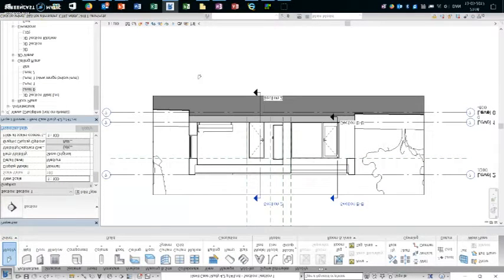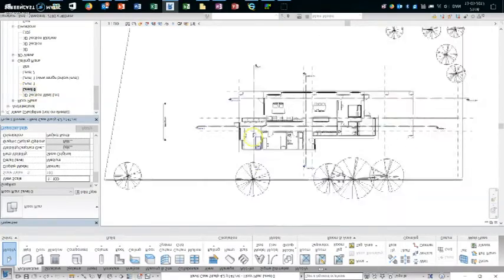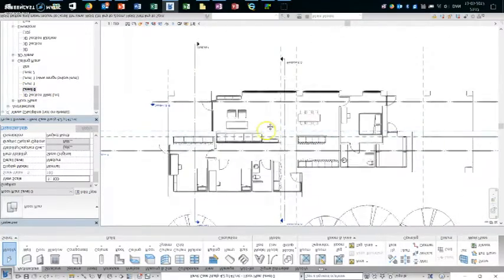Next thing I want to do is to delete the floor, because when I split levels, I have to create a new floor just in the part of the building that is on the new level. So I click the floor, press delete, and now I have a floating house once more. Double click on level 0 and I'm back, and now I can create the new